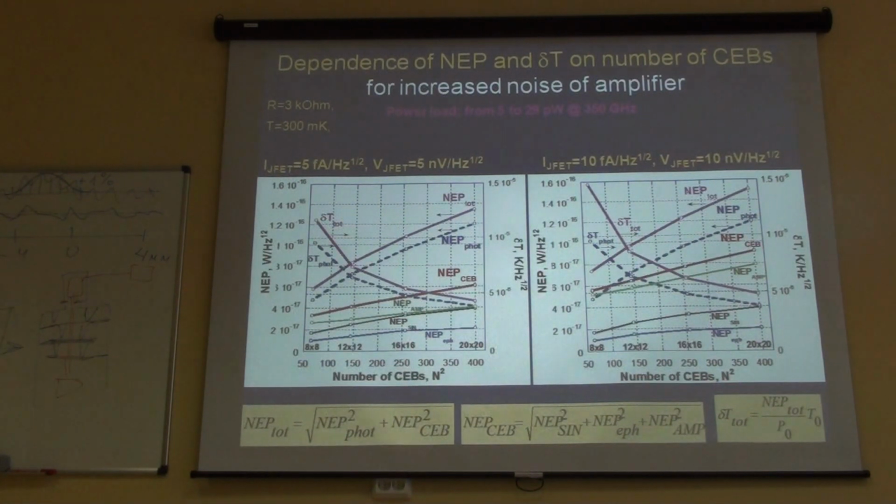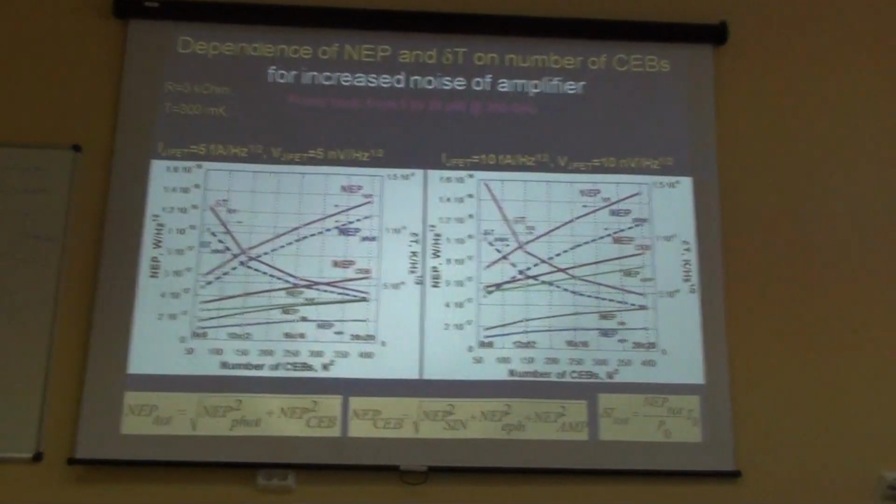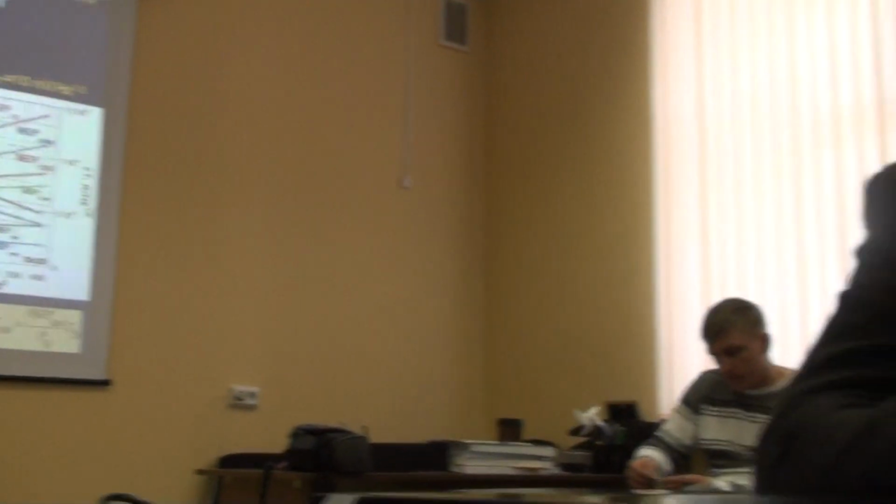Also, when we compare our 4-junction structure, the single junction structure, and an array of 64 or 128 bolometers, we see a perfect IV curve for the 128. That means all of them are the same, ratio 1000. For the single structure, it's not so good. More smeared. I don't know if it's already a little burnt out, or smeared by fluctuations or something. That means it's not a question of scale as such.